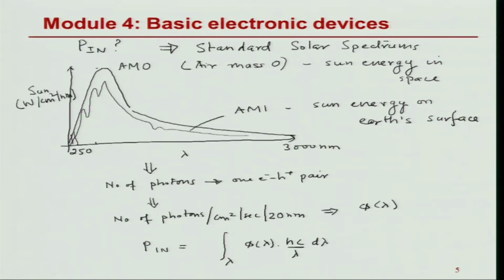It depends on which technology or which semiconductor we are going to use. Silicon is the most common one, and the one we have also discussed extensively. It almost constitutes 90% of the solar cells which are fabricated even today, and its maximum efficiency can be something like 25%, if everything is done in a proper way. But commercially, what you get is somewhere between 15 to 16%. So, there is a gap between the theoretical efficiency you can get and what one manufactures, and we will try to see why that gap is there and how one can improve it.